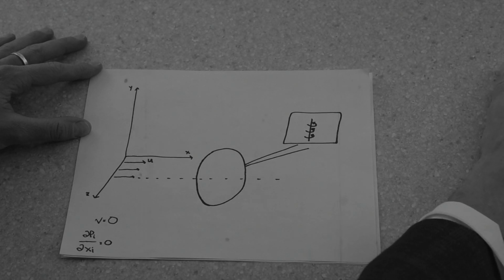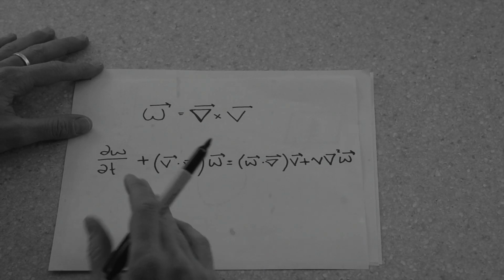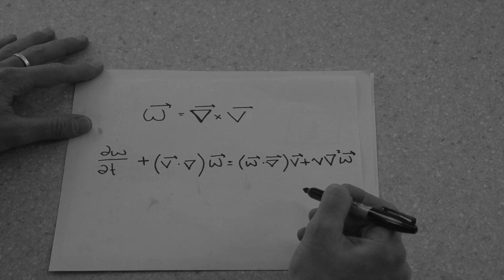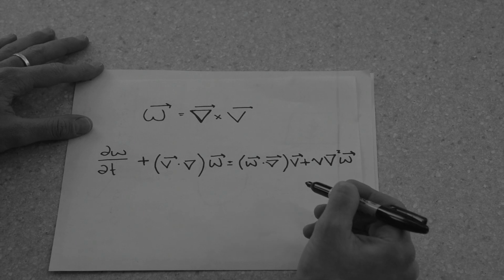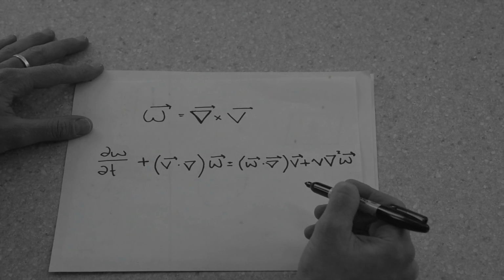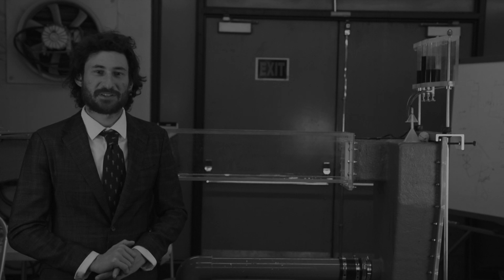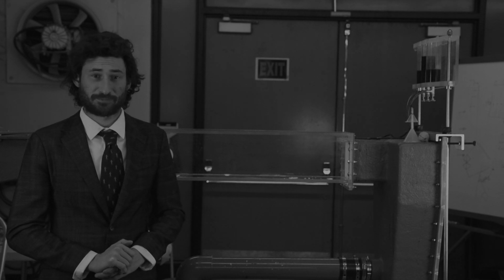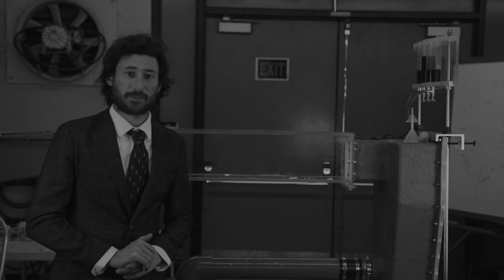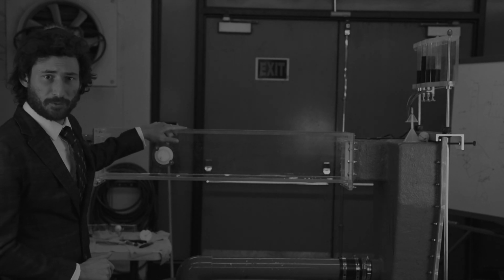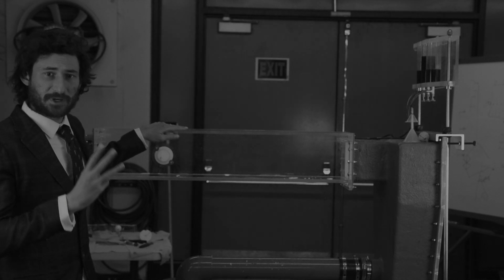Now, if we add viscous effects to the media, we can see that according to the vorticity transport equation, there will be diffusion of the vortex ring. The aim of this experiment is to model a vortex tube in a water channel. The water channel used in this experiment has a total capacity of 40 gallons, and we tested 3 different flow speeds.